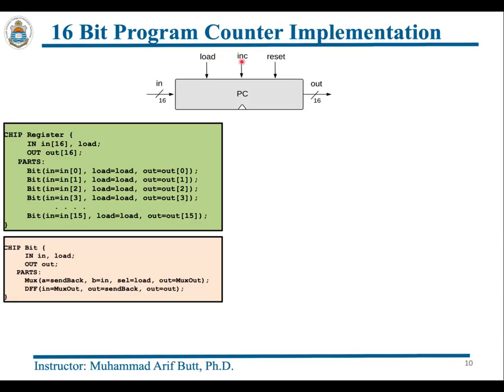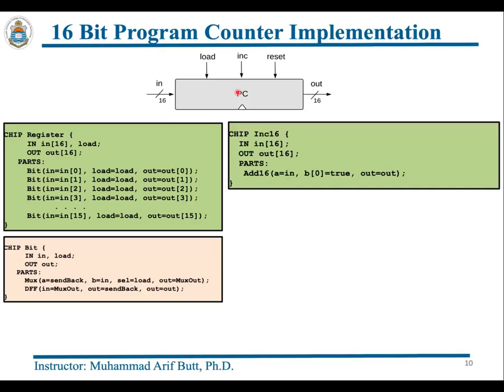has another input, the increment input INC, and if this is set, the contents of the program counter will be incremented by 1, and this functionality can be achieved by the increment 16 chip, INC16 chip that we designed in, I think, lecture number 8. And here is the HDL code of that chip.